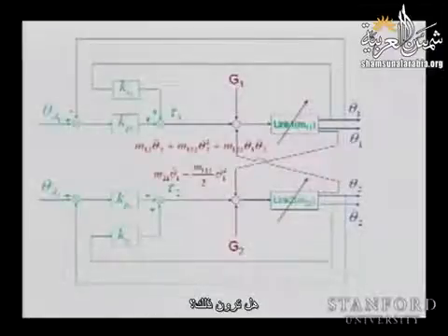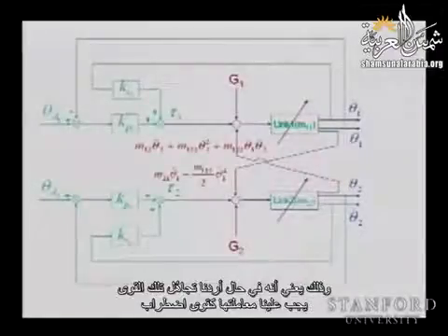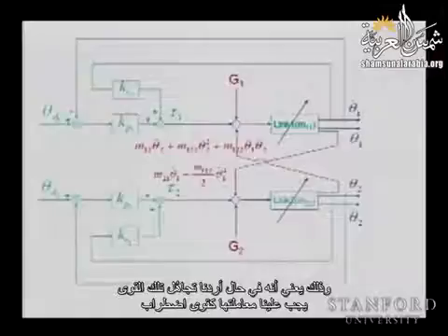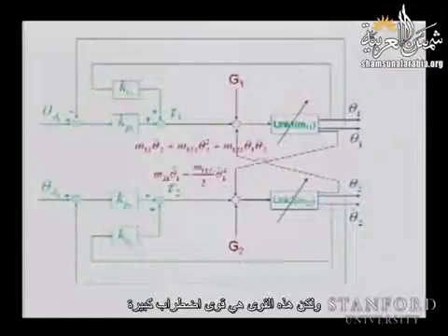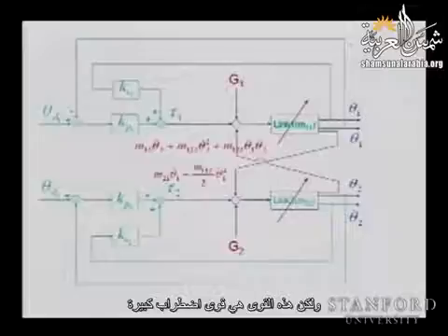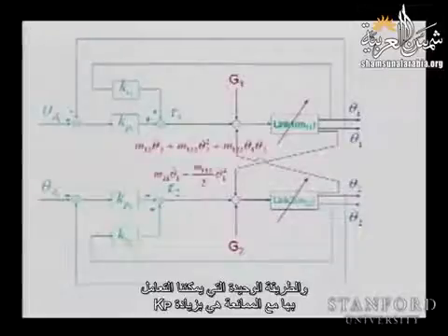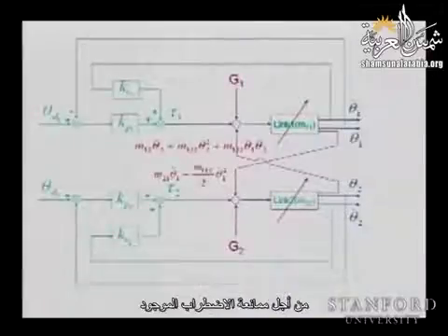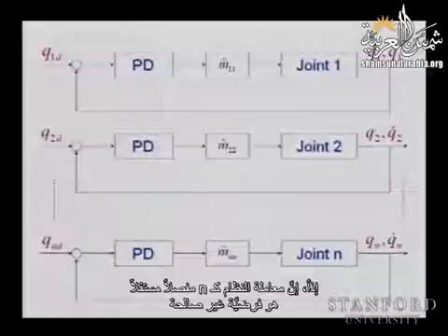You see that? Which means that to ignore it, we need to really treat these as disturbance forces, but these are large disturbance forces. And the only way you can deal with the rejection, as you know, is increasing KPs to reject your disturbances. So treating the system as independent joints is not a valid assumption.